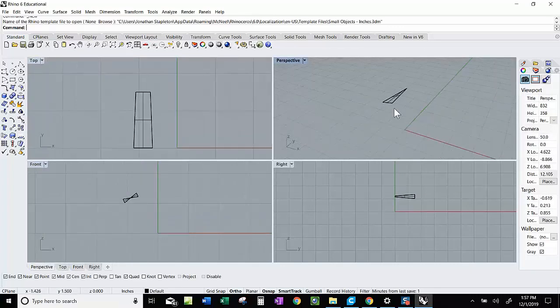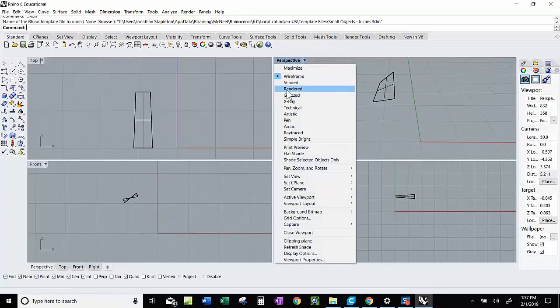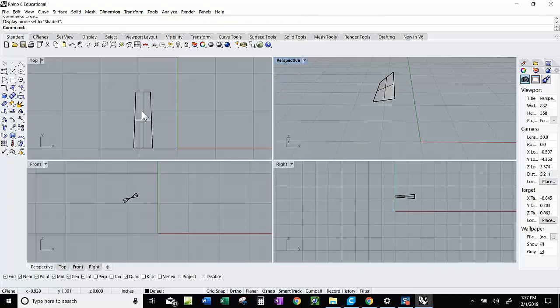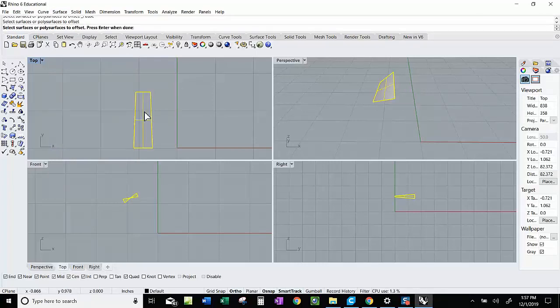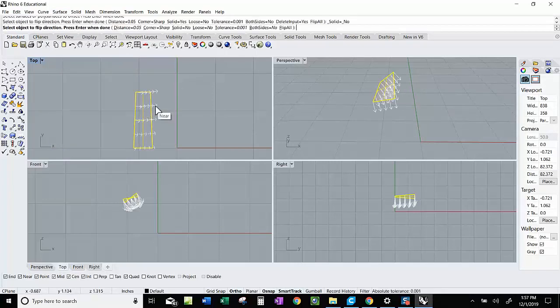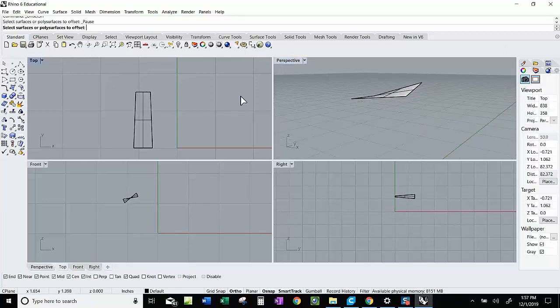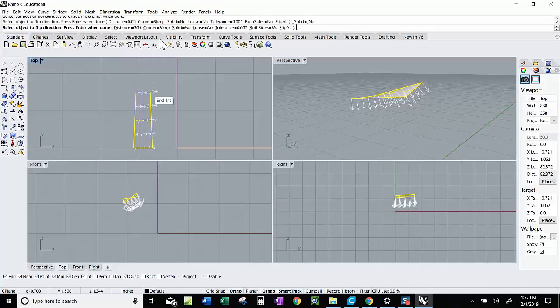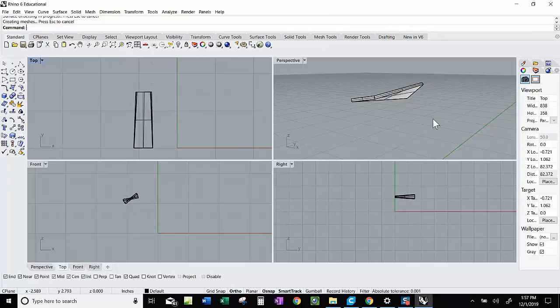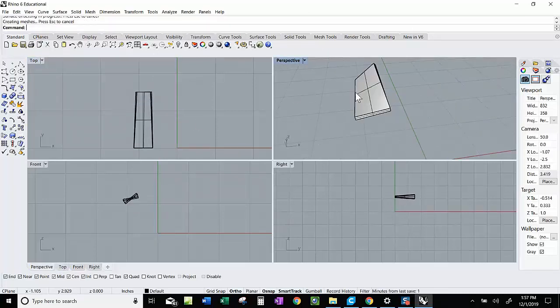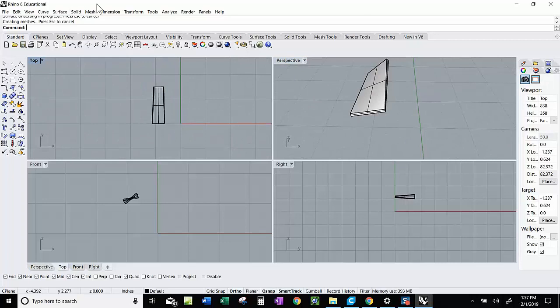And here's what I have. So I need to offset this. Click it. You don't have to click it, but you want to do surface, offset surface. There are different kinds of offset. So click that, press enter when I'm done, and I want to offset this 0.05 inches. So I just type that. And I forgot to make it a solid. So let me try that again. Solid. So there. All right, now I need some kind of hub in the middle to hold this thing together.